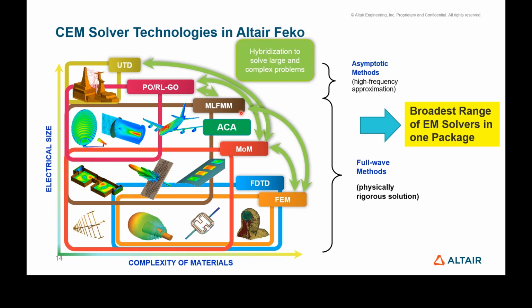to many wavelengths. I would say tens or hundreds of wavelengths based on the computational resources you have, and can still solve very effectively. So all these methods here, you can consider them as full wave solutions. That means we solve Maxwell's equations accurately, and these solutions give you very accurate answers, provided you have a good CAD model and good meshing of that CAD model.